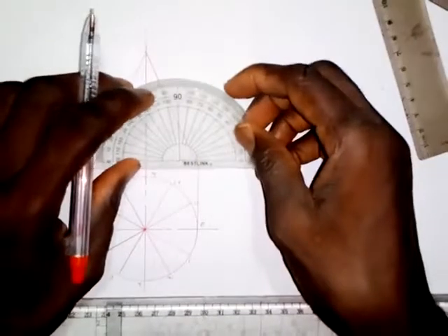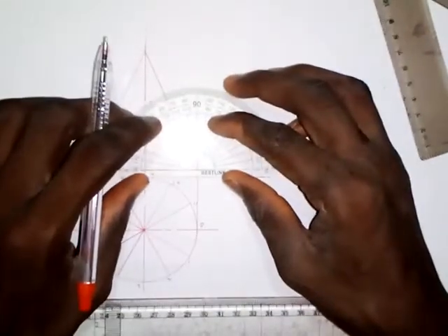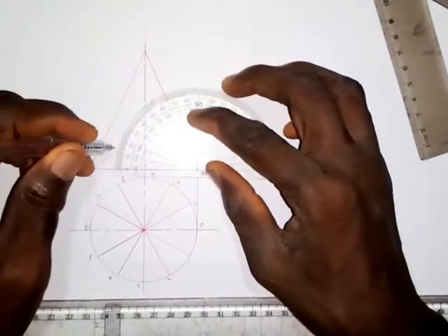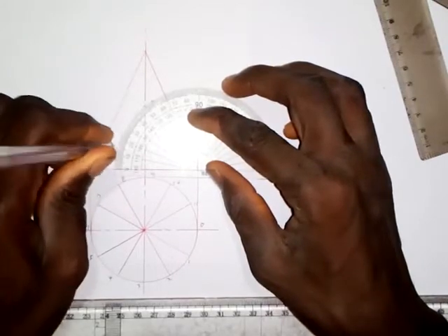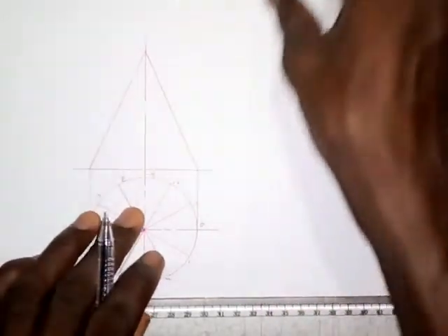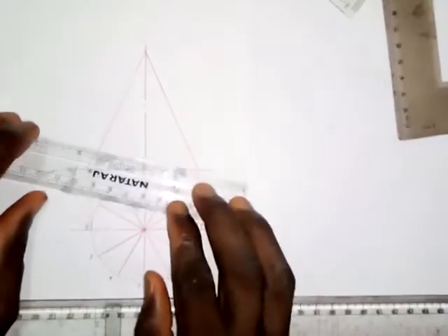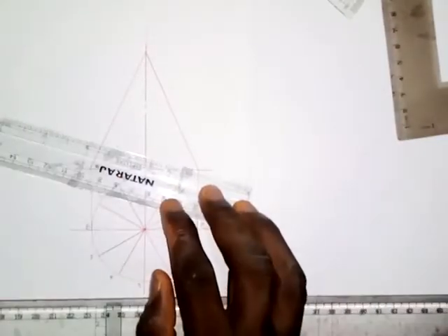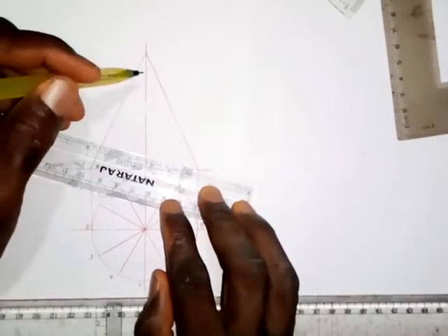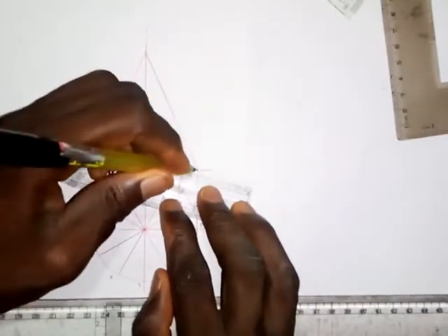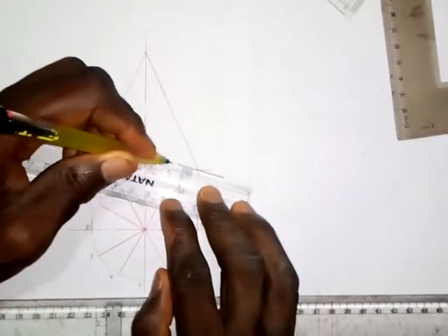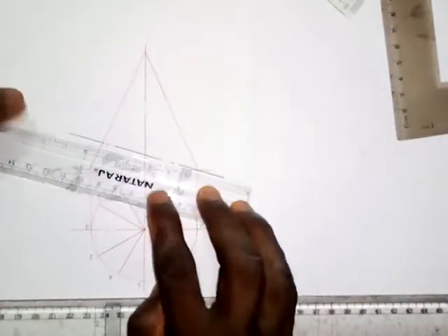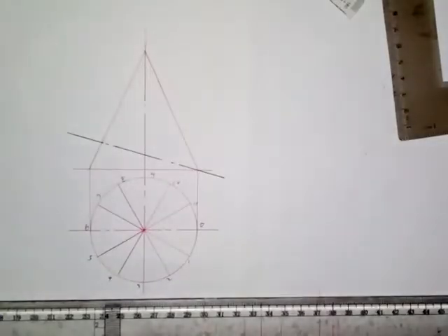Then with my protractor, I place my protractor at this point, then I take a measurement of angle 15 degrees. I'm going to draw a line from here through this point, which should be a cutting plane. A cutting plane is drawn with a thick long chain line. Okay, so that is cutting plane